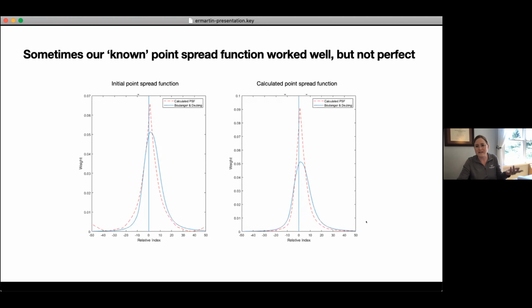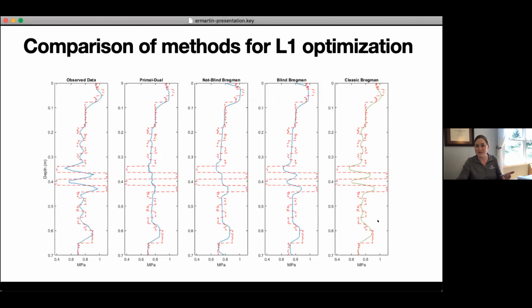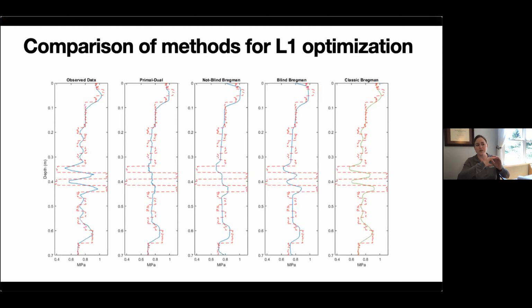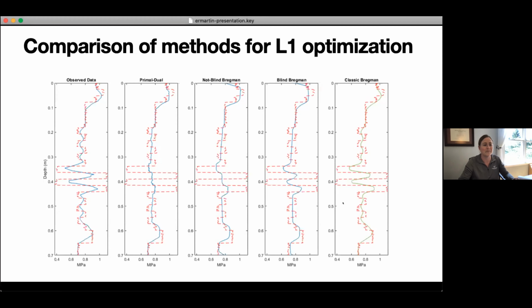We did come up with a simple expression that was based on a truncated chi-squared distribution that tended to fit the data a little bit better. But we don't have a good physical intuition for what our blurring function should be and how we interpret that physically, in terms of the stress bulb and the soil displacement yet. So that's still an open question.